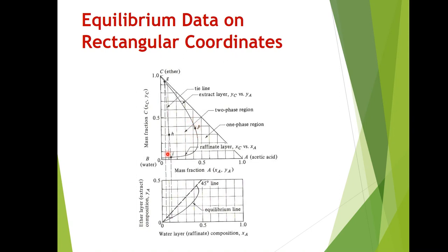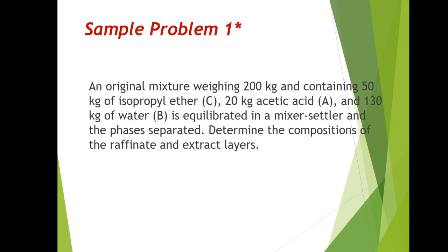Some of the problems are to be solved using both graphical and analytical procedures. In graphical, you are to extract information from the graph. In analytical procedures, we're only using pure material balance. In graphical, we use simultaneously the construction of the lines and points that we have placed here, together with the material balance equation. That way we can come up with the required information of the problem. Now I will illustrate the use of this diagram in the case of a sample problem.